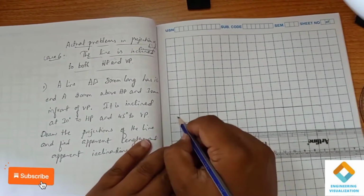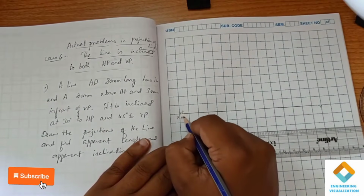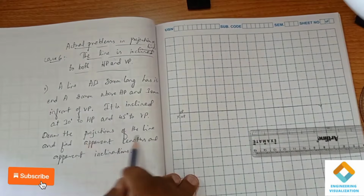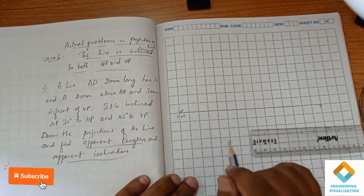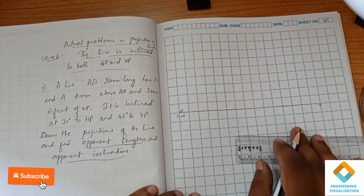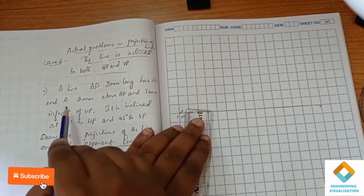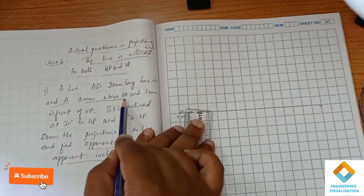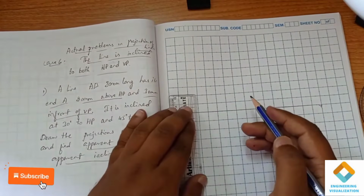So XY, VP, HP. In this problem we have to draw the projections of the line and find apparent lengths and apparent inclinations. As we have discussed, apparent lengths are nothing but the reduced lengths. First, the end A of the line is 20 mm above HP and 30 mm in front of VP.